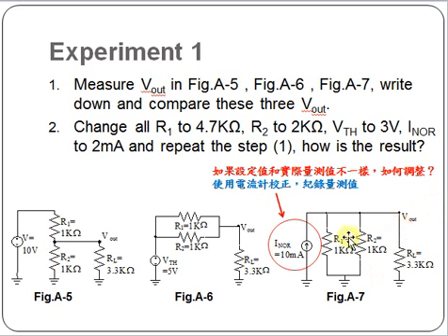This will make the power supply output the desired current steadily. However, in this case, because the current 10 milliampere is very small, the number on the power supply may not be accurate. Use your multimeter to measure the current and adjust accordingly. If you find it very hard to achieve the goal, you may use the BK precision power supply. The machine has better precision than the original one, so it should be easier to adjust. Please review how to set the current limit.